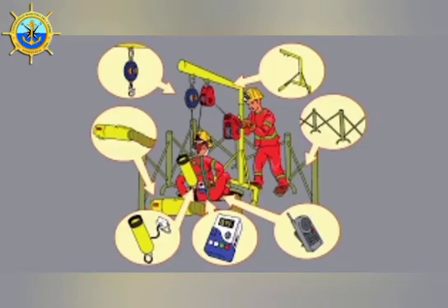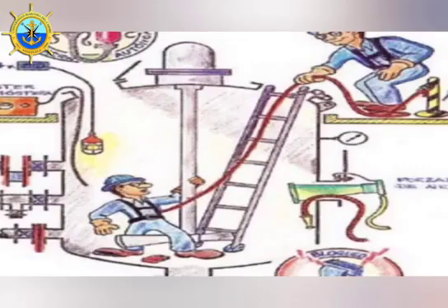Personal protective equipment could consist of the following: rubber suits, boots, gloves, face shields, and other items indicated. Breathing equipment, including self-contained breathing apparatus or airline respirator and a source of compressed air for breathing equipment. A rescue system containing a lifeline, body harness, lifting mechanism, or anchor. The ventilation equipment required to achieve the necessary condition for entry. Lighting equipment to see well, work safely, and leave the space quickly in an emergency.